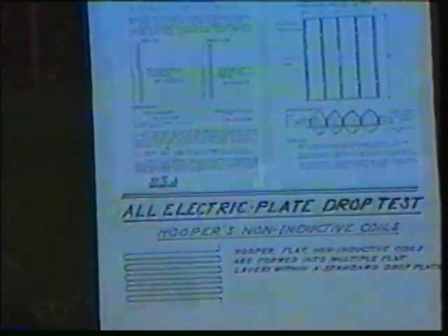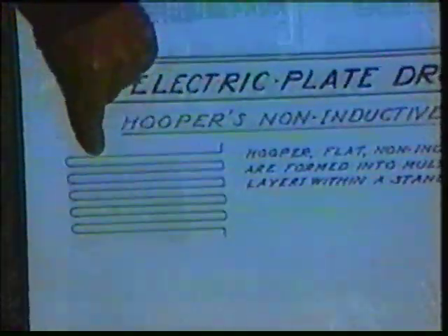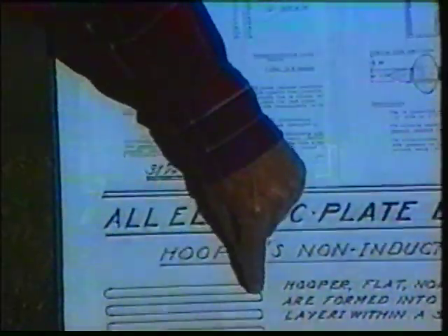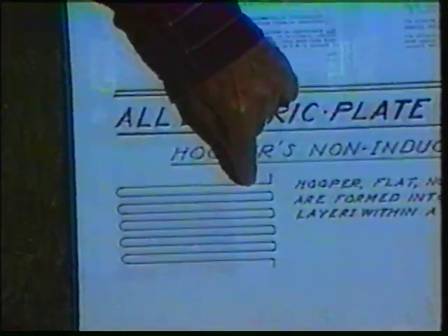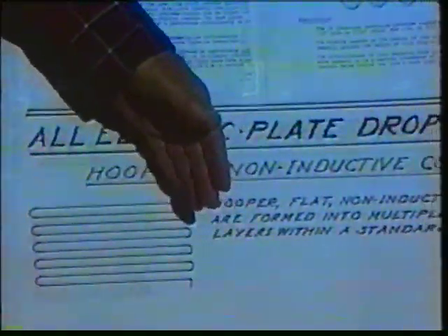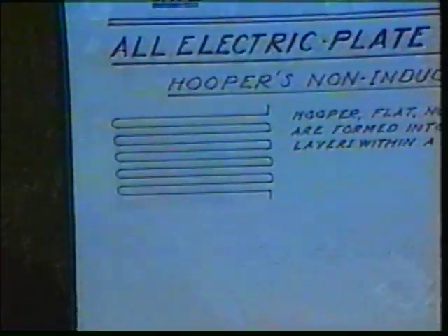You see, because it's flat. It's not bifilar in the sense that it's wound around a core. It's round, but still flat. And the neighboring turns go consecutively in opposite directions. Exactly. So you're producing an Ørsted flux when current is flowing here, but when you back it on itself, the two flux patterns cancel, and they're successively canceling as you go. In other words, back and forth EMF in this way will cancel magnetic flux. So this is going to be interesting to see, and it's just work in progress.